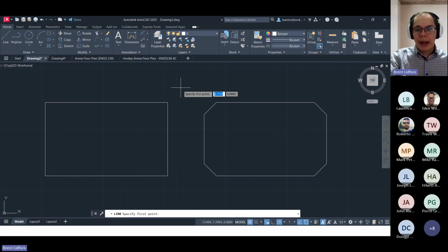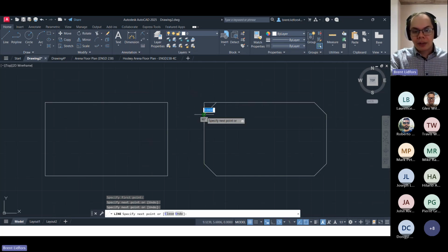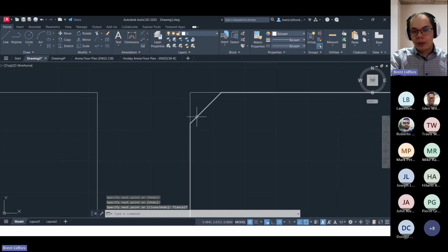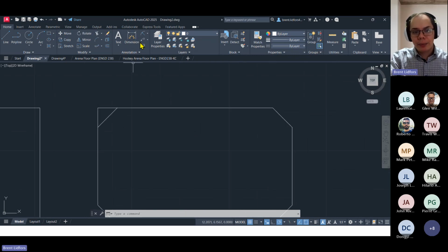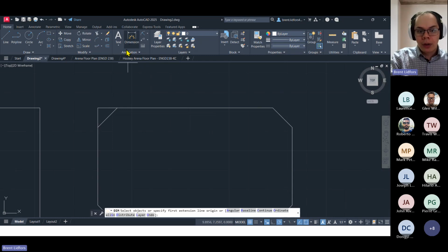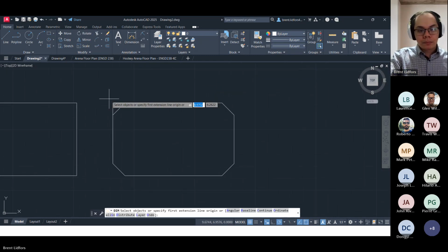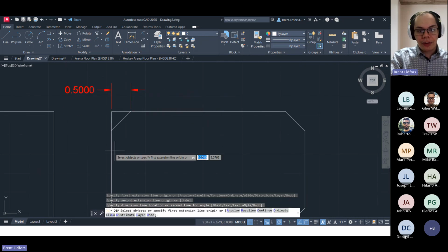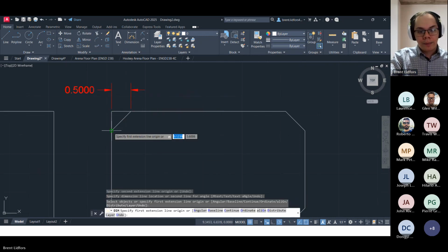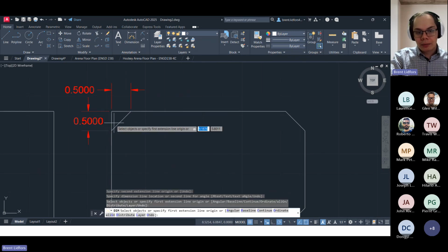The reason for that is that if you imagine this was still intact, our chamfer looks like a triangle here that's being cut off. So the two ways we can define that triangle that's being cut out there is either with two distances or a distance and an angle. By two distances, I mean this distance here and this distance here.